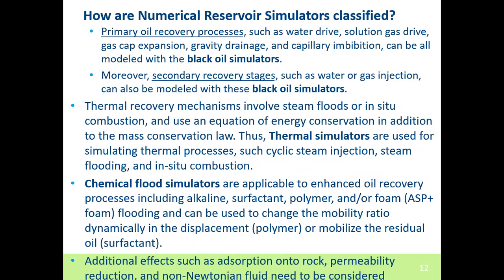For primary oil recovery processes, such as water drive, solution gas drive, gas cap expansion, gravity drainage, and capillary imbibition, these can all be modeled with black oil simulators. And secondary recovery processes which involve immiscible displacement can also be simulated using black oil simulators.